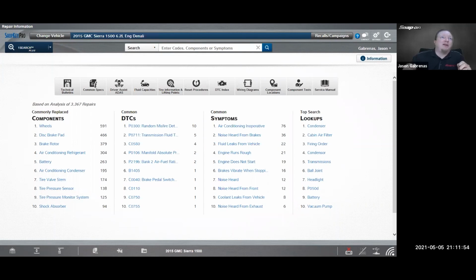Let's see. Mike, would I recommend one of the OBD2 breakout boxes with the lights over one without? So that depends on what you're trying to use it for. The ones with the lights are nice. I know we make one, but over in the UK, I don't even know if we have it available in the States. But when you plug it in and you have lights with signals right on there, that gives you a quick visual. Otherwise, if you just simply need to test, you can use the one without. Either or, I guess it's just a matter of personal preference.